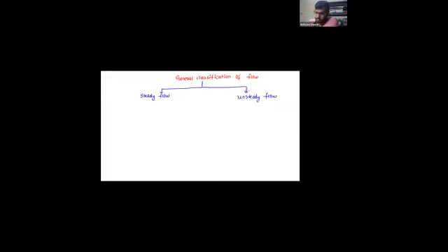So, in terms of the definitions, I gave you the definitions differently, but here, if the flow parameters like velocity with respect to time and the depth with respect to time... what is the meaning of dou v by dou t? At a particular section with respect to time, if the flow parameters remain the same, means no change. See, dou v by dou t means variation of the velocity with respect to time is zero. Then we call it a steady flow. And if dou y by dou t is not equal to zero, then we call it an unsteady flow.